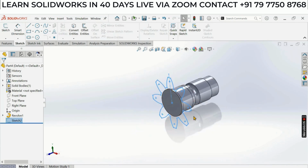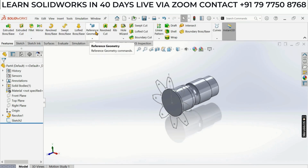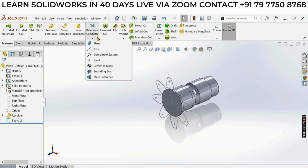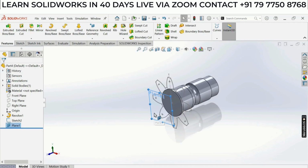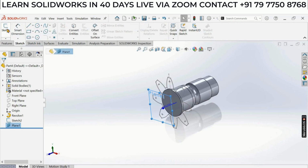Okay, on this plane the one sketch is done, and I need to create two more planes. Reference geometry, select plane and select the surface. Then I will mention the distance 45. Say OK. Now I will select this plane and start sketching.